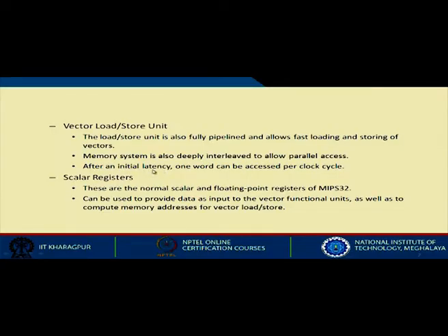So, memory organization has to be much more complex if we have to read a whole vector of 64 words or double words in one cycle or in a very few number of cycles, right. So, you need to modify the memory system as well. After the initial latency, which indicates the access time of the memory, you can access the words 1 per cycle.